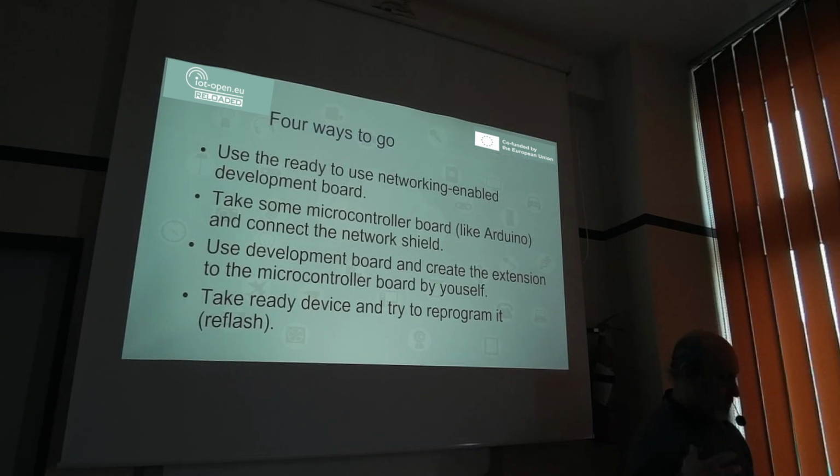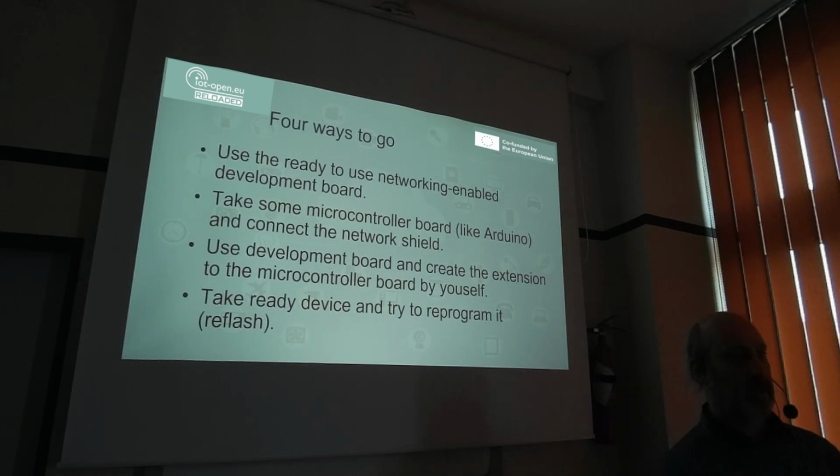Another way, you can take some microcontroller board or microcomputer like Arduino and connect a networking module to it. This module can be a Wi-Fi module. For example, you can use the ESP01 as the Wi-Fi module for Arduino. You can use some Bluetooth module maybe. So this is another possibility. Another possibility is to use a development board and create the extension by yourself.